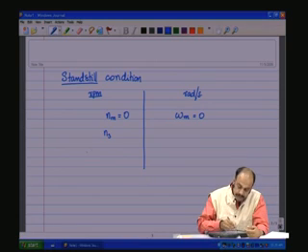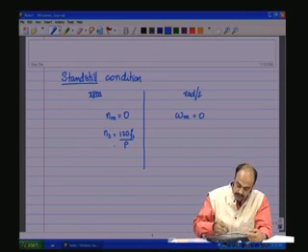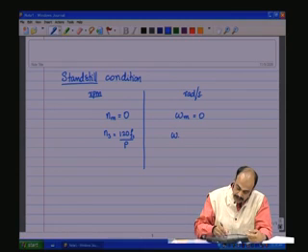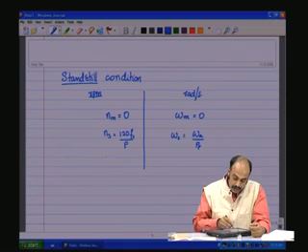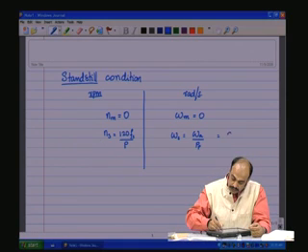Ns is equal to 120 Fs by P, the number of poles, and omega s is equal to omega actual, that is applied to the stator, divided by the number of pole pairs, or 2 omega actual by the number of poles.